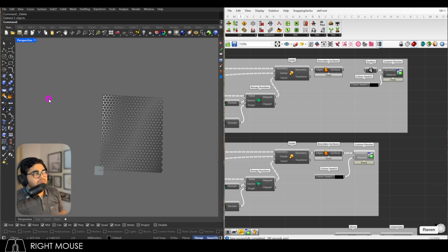Simple. So in Rhino, what you got to do, you see this on the left hand side, you see this icon which says surface from 3 or 4 point corner. Right click on it and then you get different options. Here you can just say surface or rectangle plane corner to corner. I'm going to create a plane something like this.